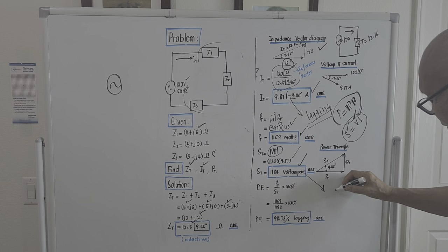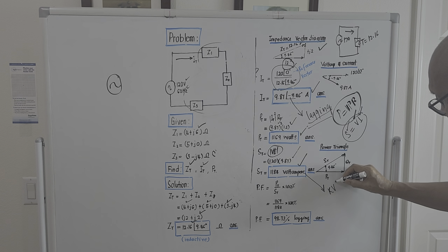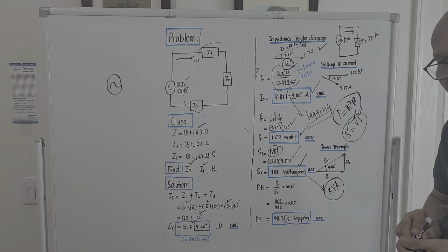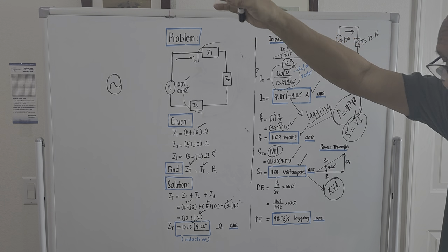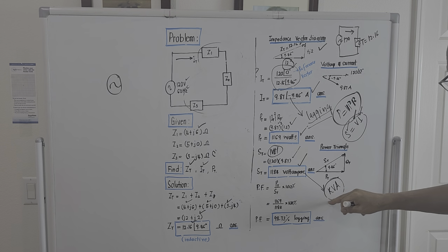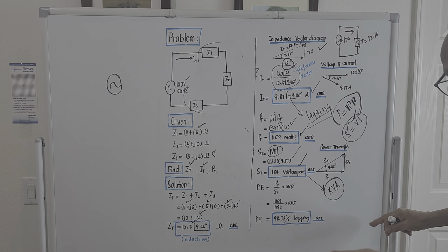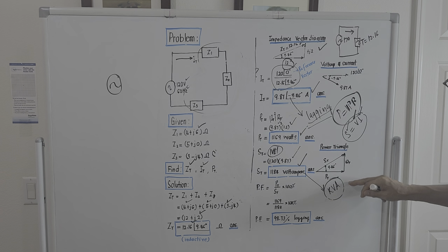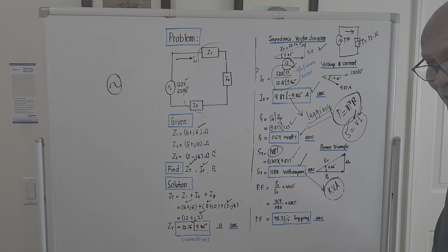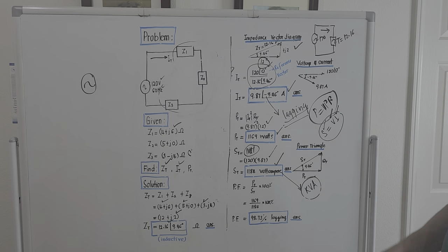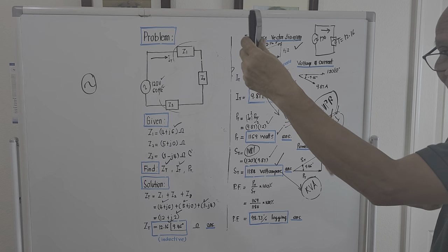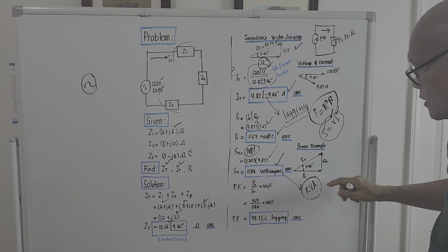If we try to divide this by 1000, this will now be in terms of kVA. And as you can see, the unit rating of transformers hanging on the post is always in terms of kVA. Okay? So at least you know what's the importance of apparent power. That is actually the unit kVA, the unit of the apparent power that could be carried with the transformer. It is marked on the transformer which is hanging on the post.